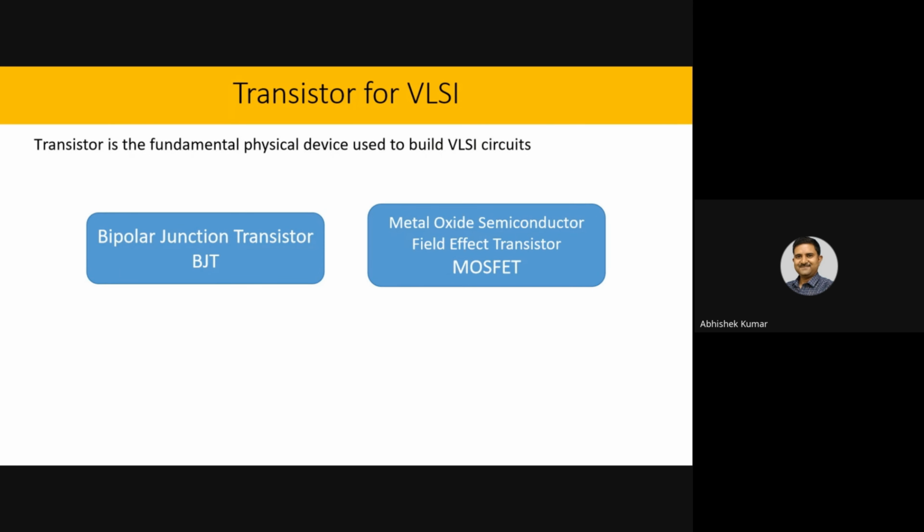So bipolar is known for, like if you remember, there are IC logic families. The fastest type of logic is ECL, which is made up of bipolar transistors. Low power consumption are MOSFET, CMOS logic, that is the MOS transistor. So when we want a faster transistor or a smaller, low power consuming transistor, that depends on the consumer application.